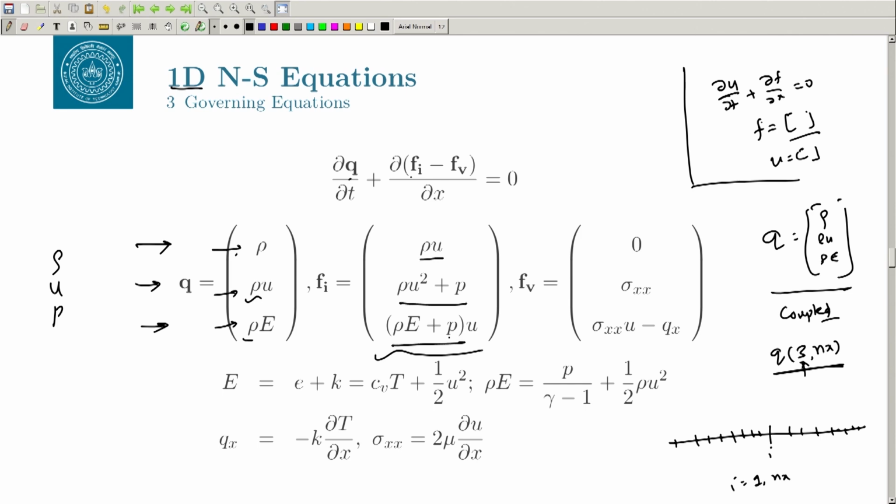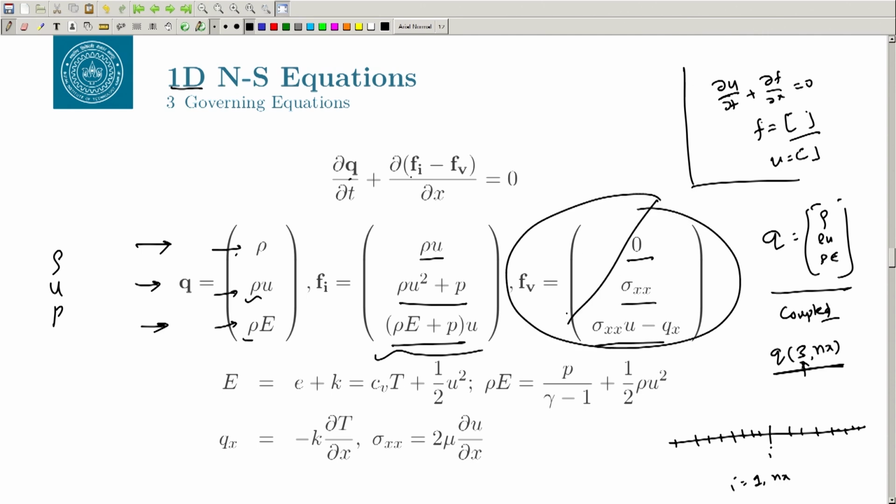This is the inviscid one, and then if you are doing viscous flow, you have to consider the flux due to the viscosity also, which is given here. For today we will not be doing this viscous flux, but we will be only interested in the Euler solution, because we have the values available. In fact, if you use a viscous solution, it will add some dissipation in the system, and your scheme will become more stable. So, these are the Euler equations. Now, I have removed the viscous term.